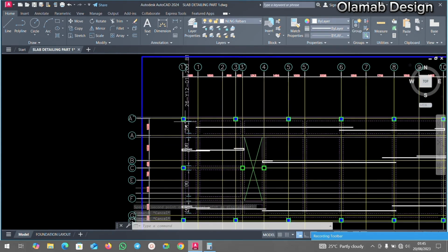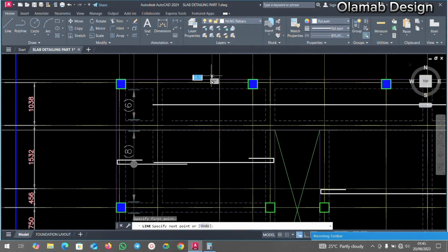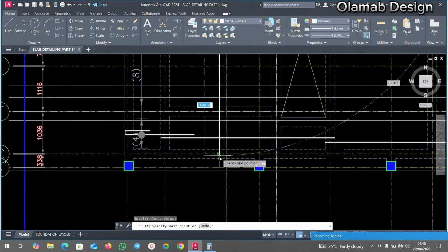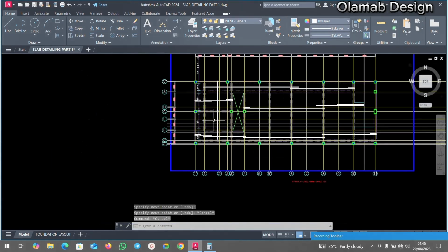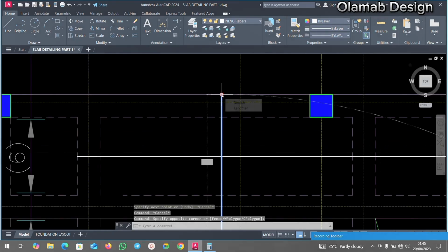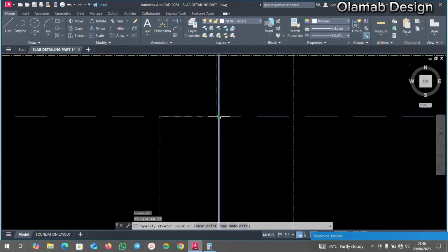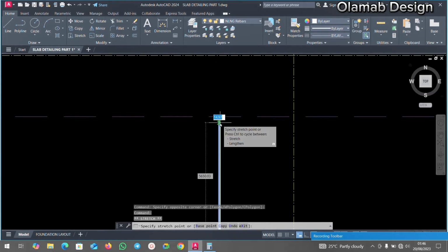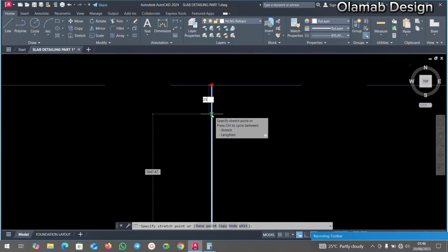So here we can also proceed and also call out this particular reinforcement. Instead of me, I can choose to pick my line also. Then I'm going to take this from here and I will take it down. I will stop it right here, and I will make sure the line I want to use for the call out is straight. So I'm going to take this back to 25 mm. I'm going to remove my cover and I'll take this inside. So I'm going to remove my 25 mm cover. Make sure you always remove your cover. So 25, I'll hit enter.